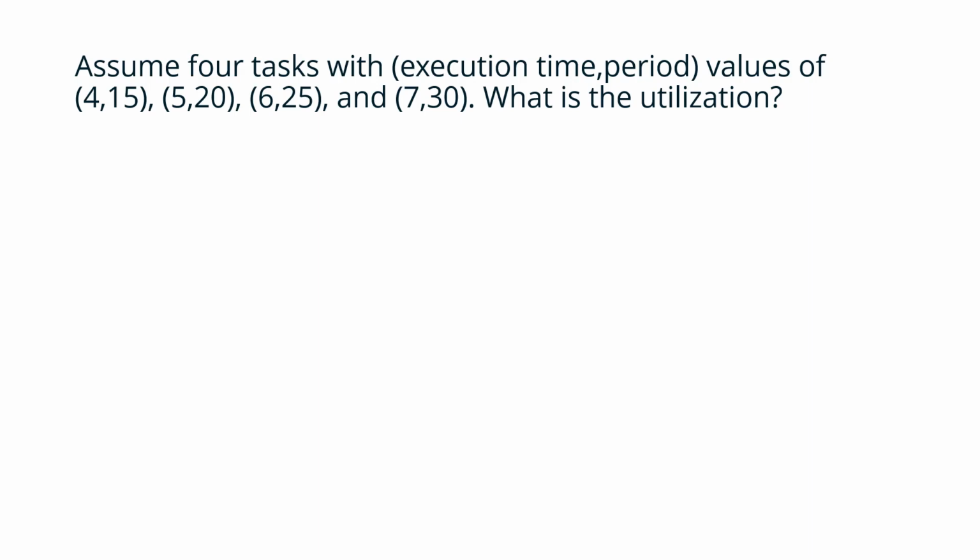You might say, well, come on, man, you just did a couple of multiplies and adds. Computers can do that fast. Well, yeah, but you have to keep in mind that normally you have one processor. If you have a robot, you're controlling every single actuator on one processor. You're time division multiplexing the processor. You're not going to have one processor for every actuator. Generally, you're going to have one processor that's going to run a whole bunch of control loops, right? And then you have to run that with a real-time operating system.